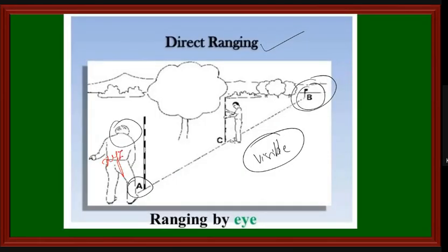He is the surveyor and he is the assistant. This is my station A and he is standing a little far from station A. So he will range the stations A and B and direct the assistant to place the ranging rod at this intermediate station called C.